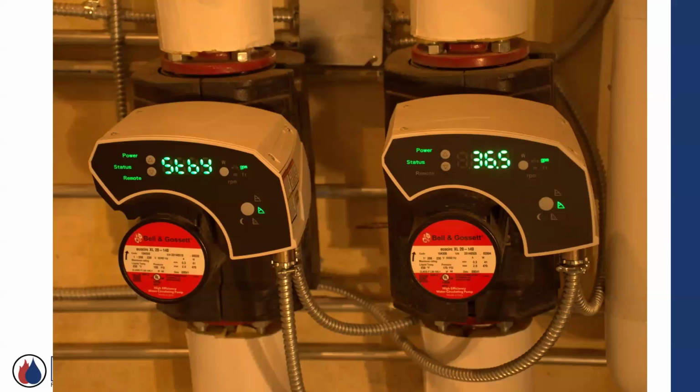And this mode here, this one's lit up. This is saying, hey, proportional pressure. Because what's happening upstairs is probably 36 apartments with 36 thermostats and 36 zone valves. So as they're opening and closing, this pump's speeding up and slowing down and responding to what's going on upstairs. So a lot of capability and intelligence just in a simple application.